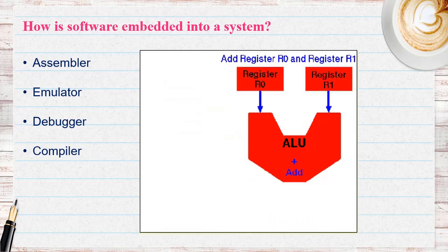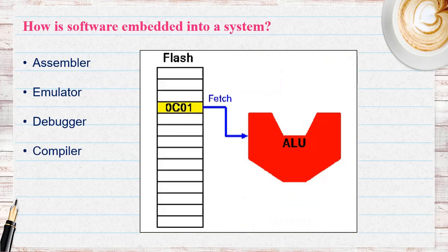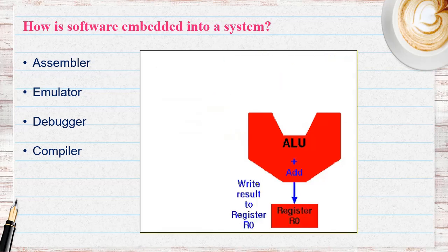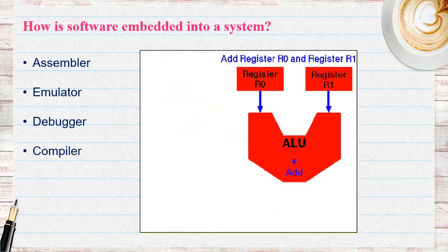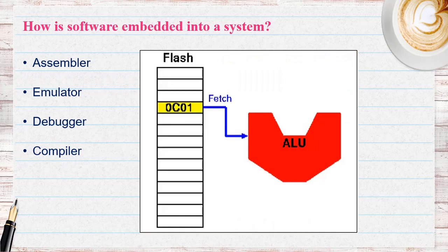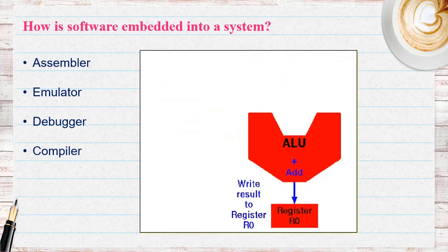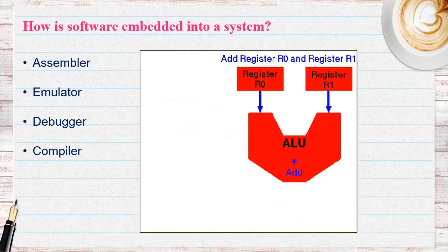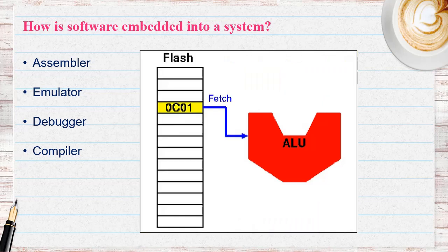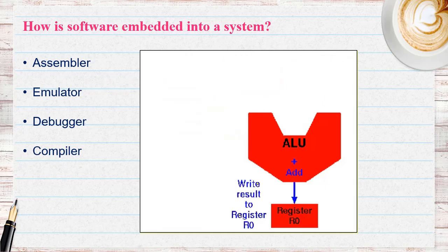For programming the hardware, we need a program written in assembly or in embedded C language. And then we compile it. This compiled code is converted into hex code. This hex code is programmed or burned into the ROM of the system, using some programmer.